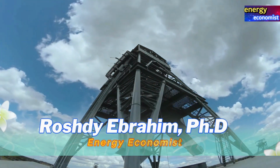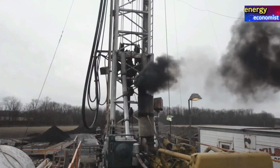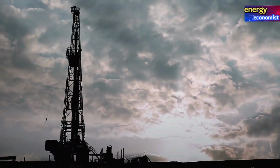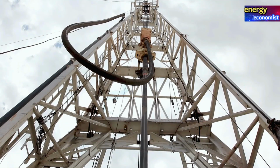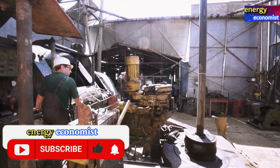The gravity range of typical crude would be 38 degrees to 22.3 degrees API, relative density 0.83 to 0.92, approximately. The abundance of intermediate hydrocarbons is the typical characteristic of black oils. The color of black oils is variable from green to black.